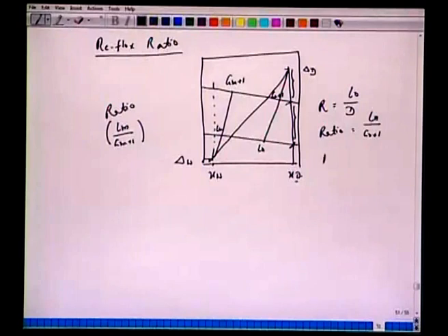Now, if the reflux ratio increases, you can notice that this point will move upward. So, that is the locus. If del D moves upward, F is fixed, right. So, let us say F, hF and zF is fixed here. Now, if this point moves upward, you can see that del W point has to move downward, because F, D, and W have to lie on this straight line. So, all it means, if this ratio increases, this ratio will decrease.